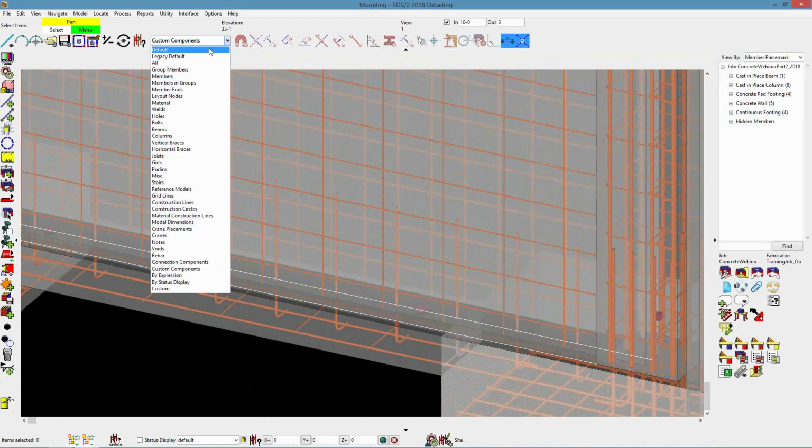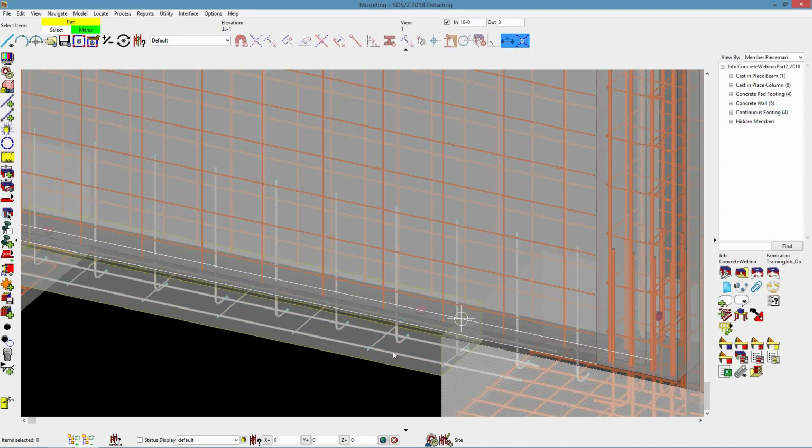And you can see that it is going all in one direction with my hook. And if I select my footing, you can see that it's actually looking at it to where my left end here is on the right side. So if you hold that footing in the left end of the footing in your left hand, when you say inside, that will bend that 90 degrees towards you. It will come towards the inside, or towards you will be the inside.